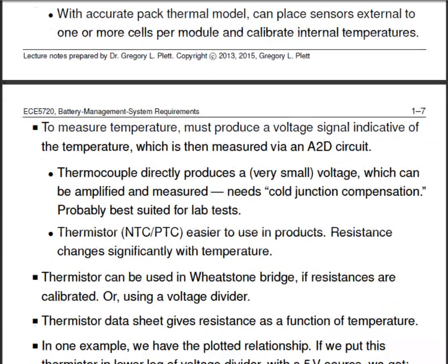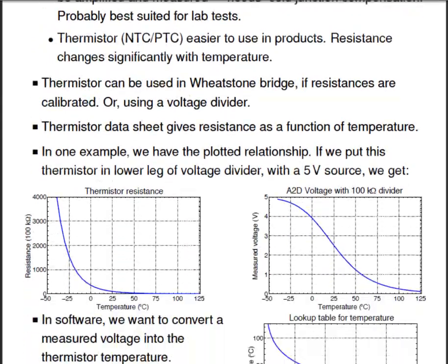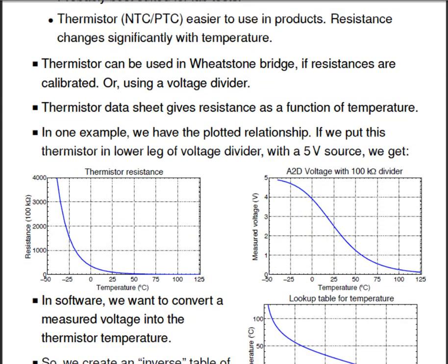So there is thermistor, there is thermocouple, NTC, PTC, that is positive temperature coefficient, negative temperature coefficient. What is NTC and what is PTC? PTC means if temperature increases, its resistance also increases, like a heating wire having a PTC. What is NTC? If the temperature increases, the resistance of the sensor decreases. In the case of semiconductors we find this, and that is called an NTC. So there are different kinds of sensors that sense the temperature inside the BMS system or inside the vehicle.